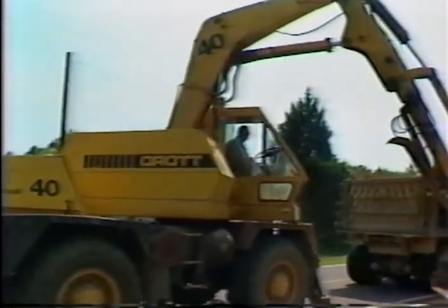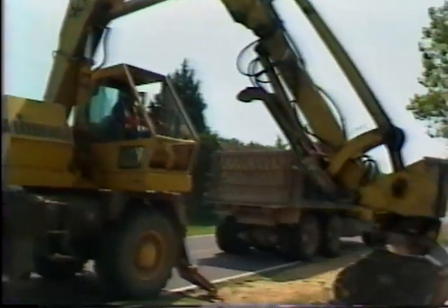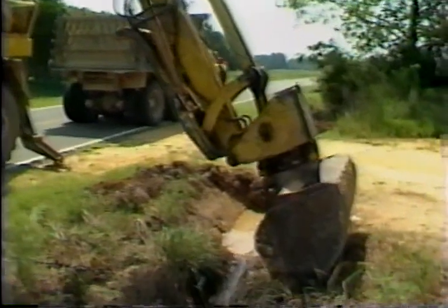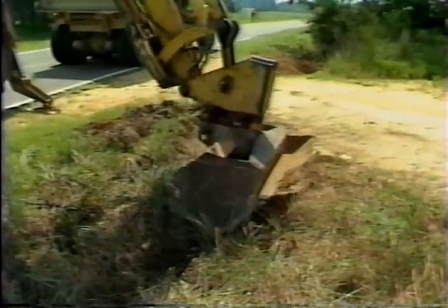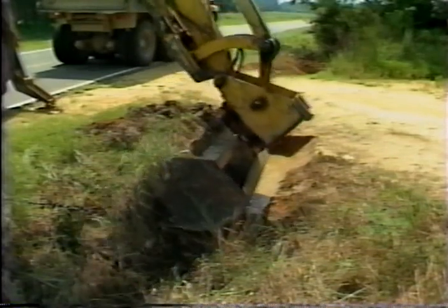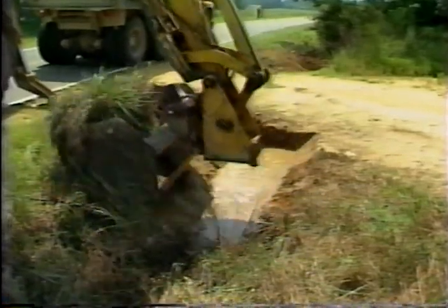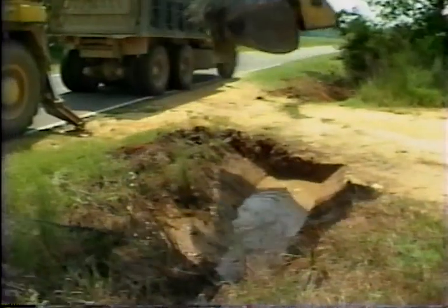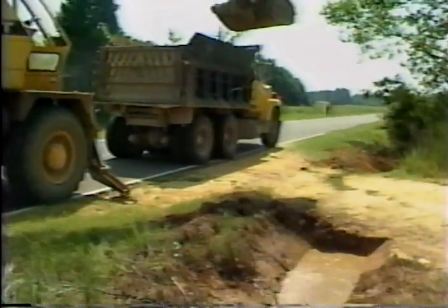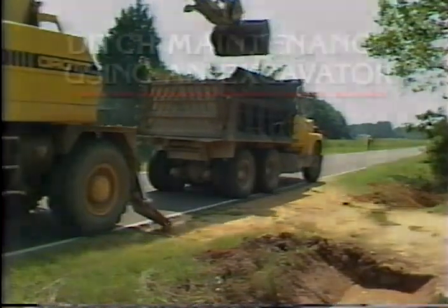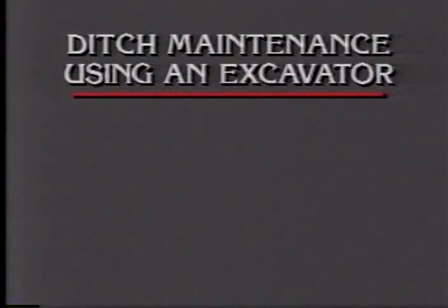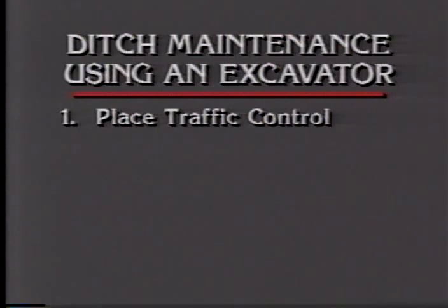Now, let's discuss ditch maintenance utilizing the hydraulic excavator. Use the hydraulic excavator in areas where a motor grader cannot operate because of wet conditions. Also, it is more efficient to use a hydraulic excavator instead of a motor grader on a road with many driveways and pipes. The steps to be performed are: number 1, place proper traffic control.